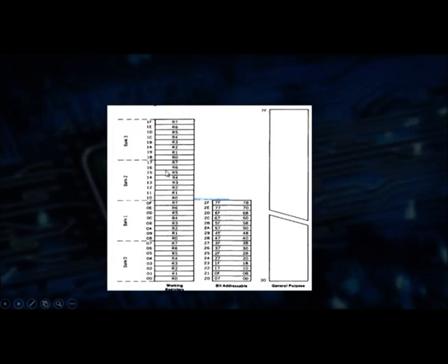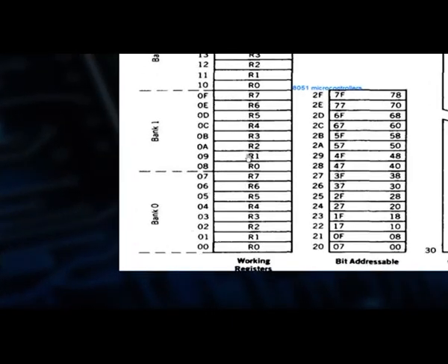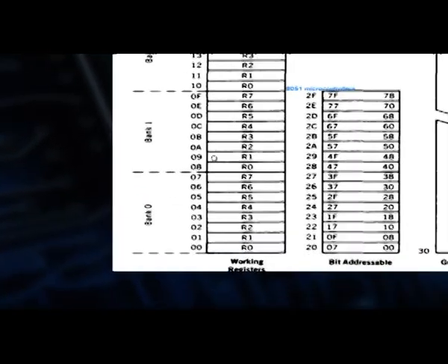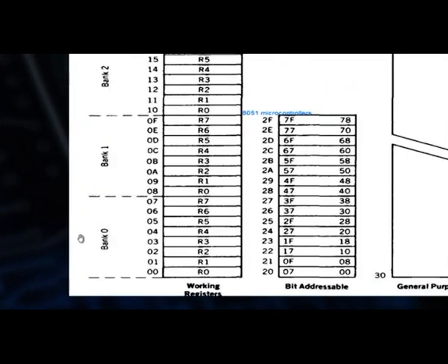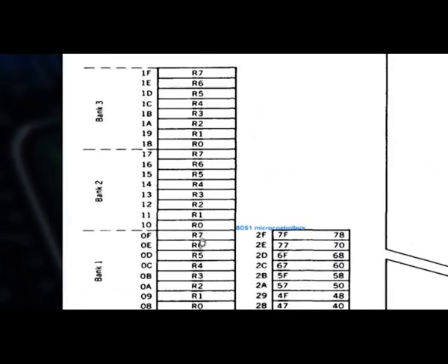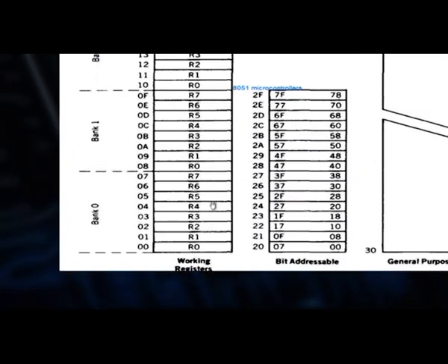This is the structure of the internal RAM. So, these are the 4 register banks. In bank 0, we have 8 registers R0 to R7. These all are 8-bit registers. Each register has a unique address, which is 00 represents R0, 01 represents R1, likewise 07 means R7 of bank 0. The R0 to R7 will be repeated for each bank, but which bank you are using depends on the bank selection. Suppose R2 means the R2 could be in bank 0, bank 1, bank 2, or bank 3.